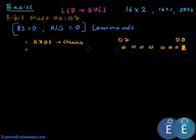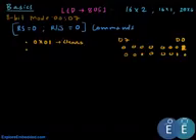And if the next bit, D1, is 1 and all of this is 0, then it sets the cursor to the first position. It just takes the cursor from anywhere in the LCD to the home position. So this is the command. Now this is don't care. So for 2 and 3, it just clears the display and gets the cursor to the home position.